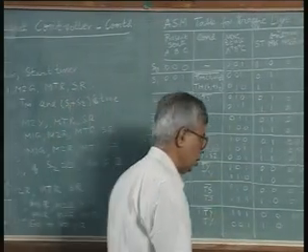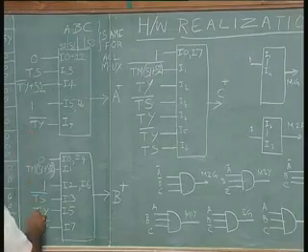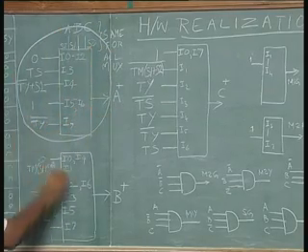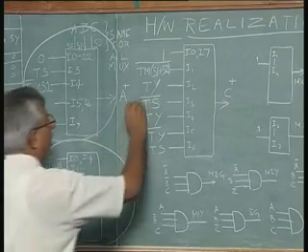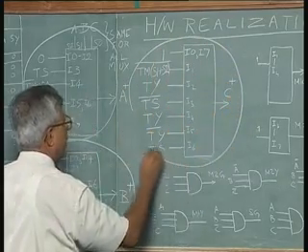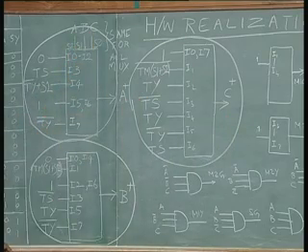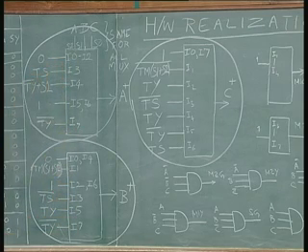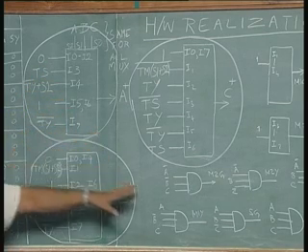These are the next state variables A plus, B plus and C plus. Each one is an 8 to 1 multiplexer with 3 selector variables S2, S1, S0 connected to A, B, C, with 8 inputs I0 to I7 connected to corresponding conditions based on the table. I have already explained one or two here; that is how it is done.